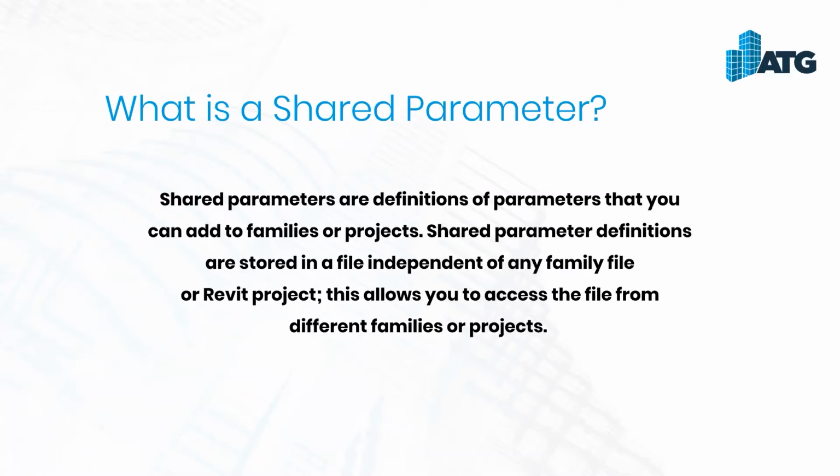The shared parameters can be discipline specific. They can also be parameters that can be added to different disciplines, meaning it could be added to an electrical type item, mechanical item, plumbing type item, architecture, structure. Really no limits on those particular disciplines. And the other thing with shared parameters is that they can be reused over and over again, and the same type of shared parameter can be used on multiple type items.